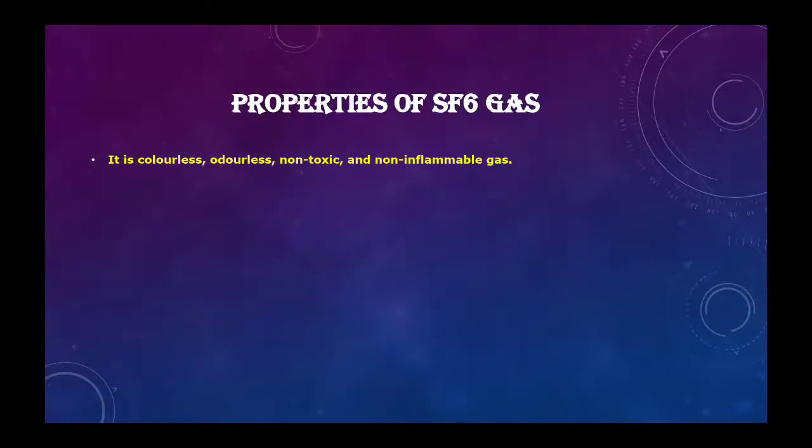Number 1, it is a colorless, odorless, non-toxic and non-inflammable gas. So this gas has no color, no smell, and it is non-toxic and non-inflammable also. SF6 gas is extremely stable and inert, and its density is 5 times that of air.